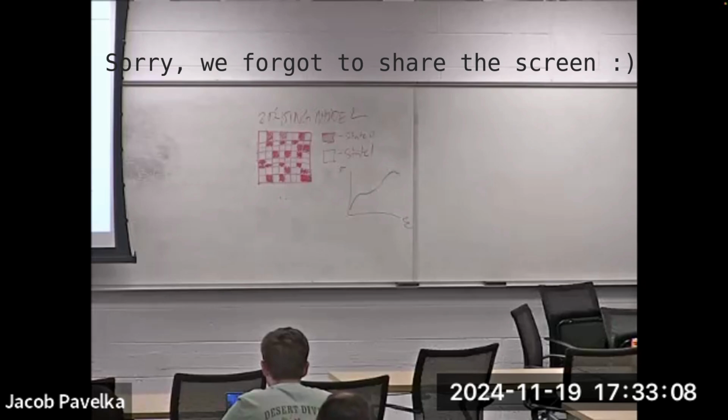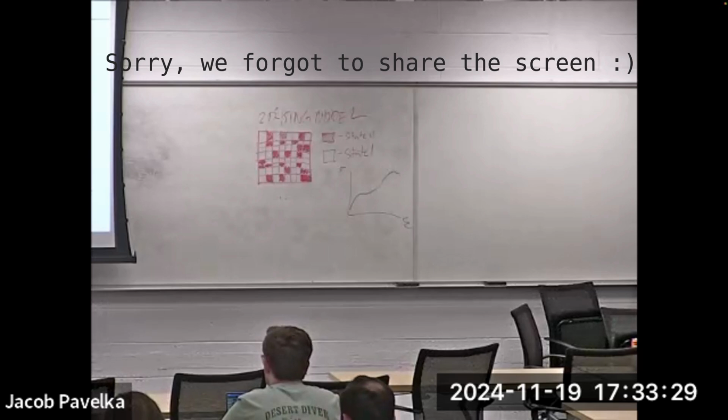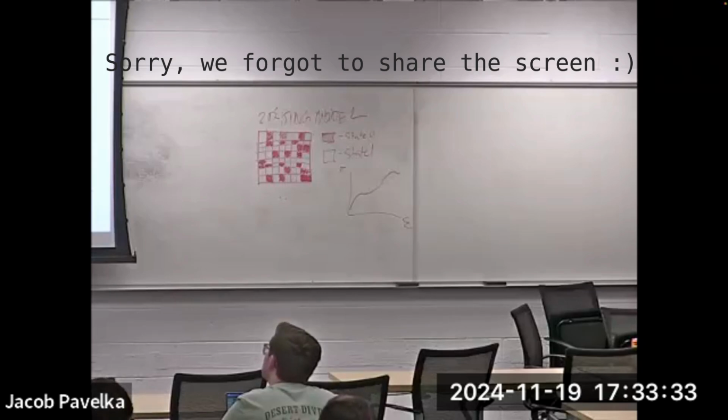Then I will skip some things. This is defining which outputs you want to give and how. Again, like I said, you need to give it the text file that you have defined your boundary conditions in, and some solver parameters: what step size you want to take, total time, and different convergence things. And here you define your elastic parameters.